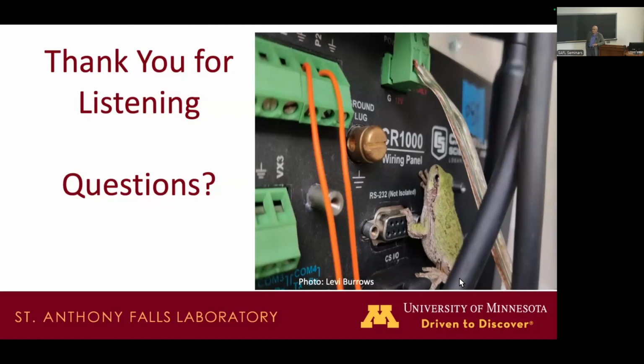But if you have a high concentration coming in, if it's not phosphate, if it's particulate phosphorus, then you can filter it and just clean your filter, right? Or you can settle it, which would be better, actually. It's probably most cost-effective to settle it as best you can. But if you have a high phosphate concentration, then everything would be different. You have less time before your media is no longer able to absorb the phosphate. Yeah, that's true.